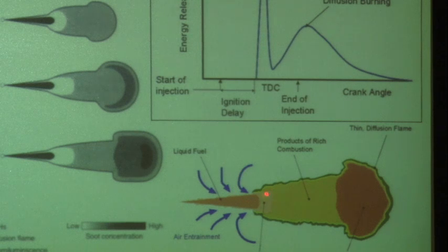And at a certain moment, a region of chemical reaction starts to take place. This you'll see in a minute. We can identify a two-stage combustion process where the first stage of combustion takes place really near the location where the fuel-air mixture has reached an optimized level.